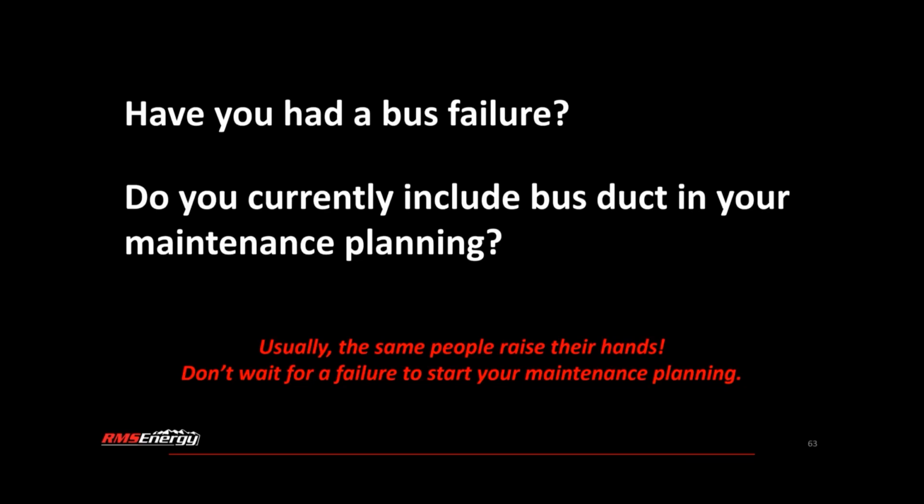I wouldn't say it's the most common practice because internally to that equipment, your transformer, your generator, you're going to have that bus tied together, so it creates parallel paths. So it won't be as cut and dry of a result as it would be if that bus was isolated. You were actually testing the conductor, but you may see some discrepancies from phase to phase that you could investigate. But usually inspection of the plated surfaces, the condition of the flexible braids, following what the OEM recommends for number of braids and placement, and then following proper hardware and torque standards should ensure a good connection there, along with greasing, some anti-corrosive grease as well.